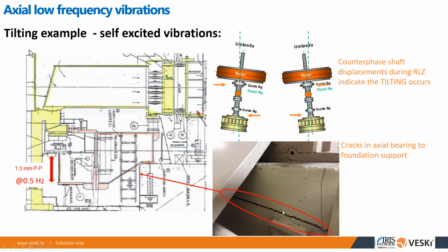So we come to low frequency dynamics. Axial displacements all show the same frequency, but also what we've seen is that the whole bracket actually moves. So if you put the accelerometer here on this spot, you can actually see that the whole structure vibrates, not just the rotor, but everything, even this bracket. And because this is a very, very big mass, it vibrates at 0.5 hertz.